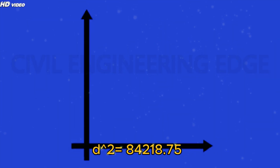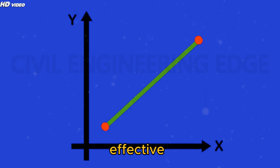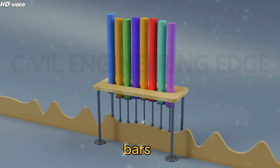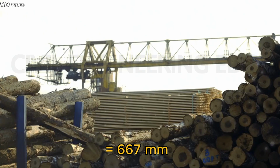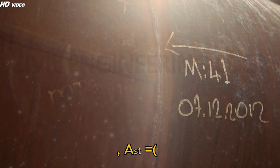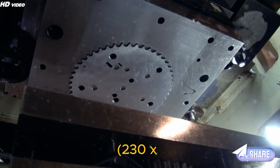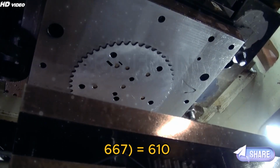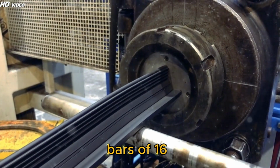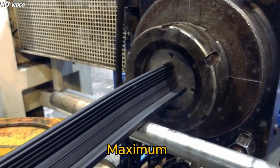Equating the moment of resistance to the bending moment, 0.913 x 300 x d squared equals 84,218.75 by 1,000, d equals 555 millimeters. Available effective depth equals 667 millimeters. So, area of steel Ast equals 84,218.75 over 230 x 0.90 x 667 equals 610 millimeters squared. Provide four bars of 16 millimeters diameter.